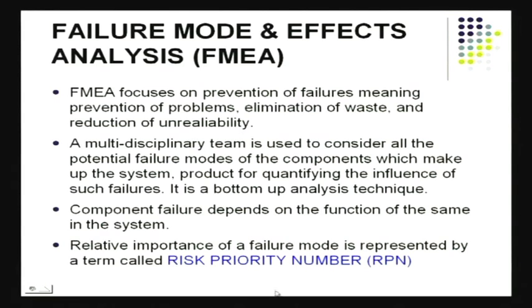The bottom line is going to be again calculation of the RPN. So this is something we'd like to be able to do. We'd like to work out the components of the RPN. And again, the risk priority number is made up of the severity, there'll be a rating, the probability of the event taking place, and the detection capability. These three things must come together, and if they give you a high RPN, that's a serious matter. You've got to take some corrective action there.